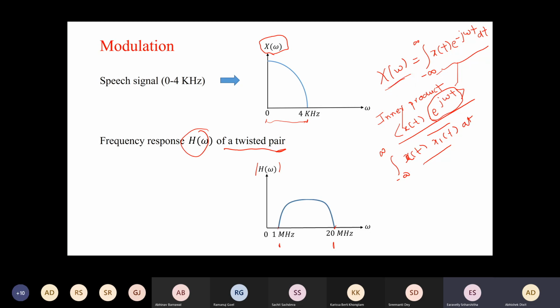and so on and so forth. And you can also think about the inner product in the case of these kind of signals. We should not get into more details about this, because this will take us into functional analysis and things like that, which I want to avoid. But it is a good idea to start thinking about this. Actually, when we are taking the Fourier transform, we are taking a signal x(t) and we are taking the inner product of the signal x(t) with this.